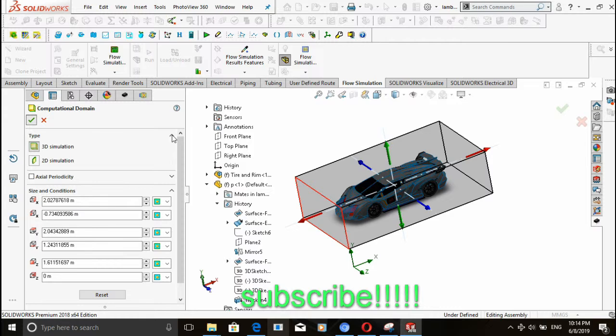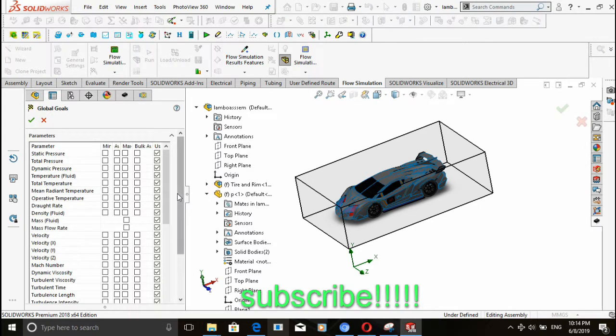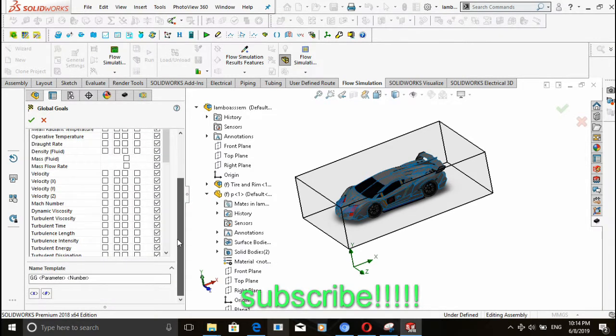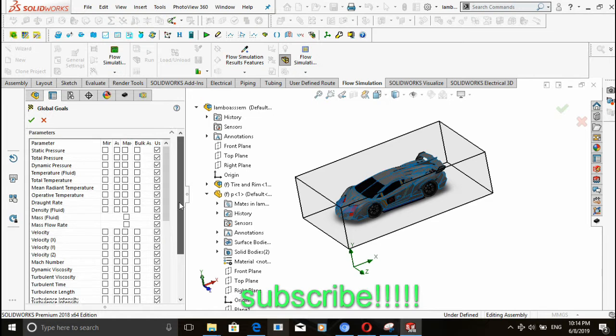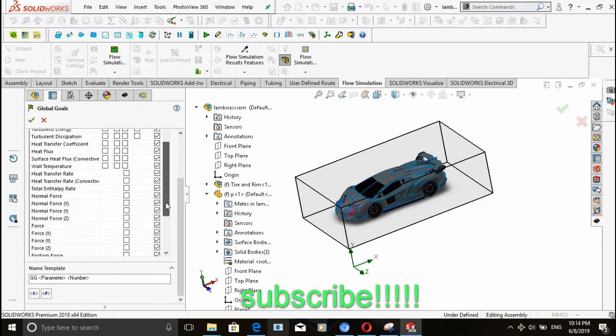So to continue, we're going to take the next parameters that we are going to start. For the fluid subdomain, it's OK, boundary condition, everything is okay. So we're just going to go to insert goals. At the level of goals, what we're going to do is check the forces that are there.